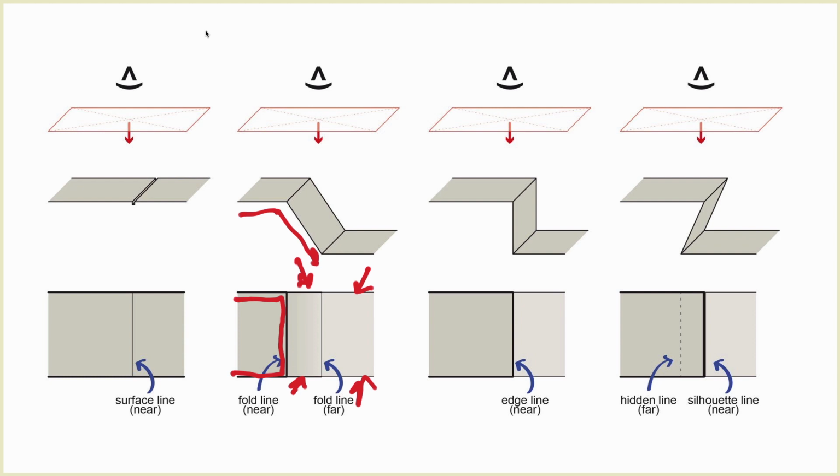This particular case, we're dropping straight down. So we've got this here as one thickness. Then this, because it's got a drop, is a little bit thicker. So we're showing that even a little thicker to show that edge. And then we have the thinner lines right there and right there that are further away. This last one we fold under, and so we're using a different line type. Here's where our hidden line comes into play. In order to tell that it's folding under, we draw that little dashed line right here so we know where that fold is. Likewise, this is our thickest line yet, right along that edge.